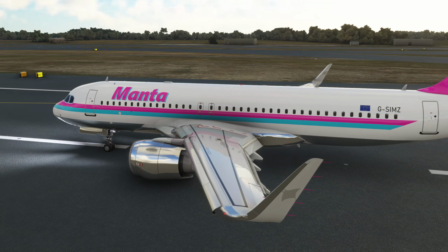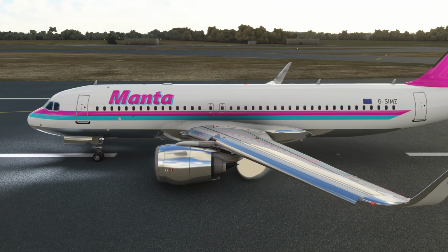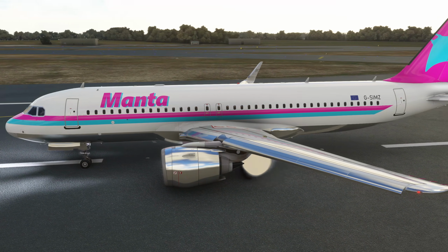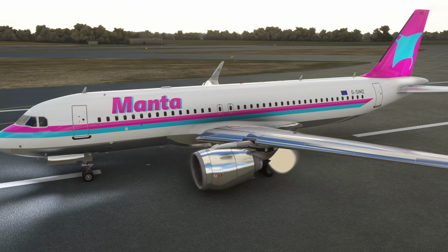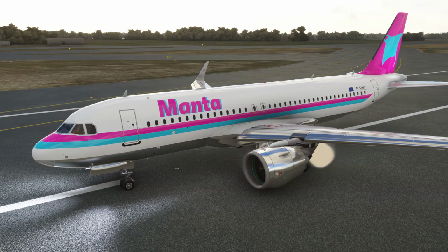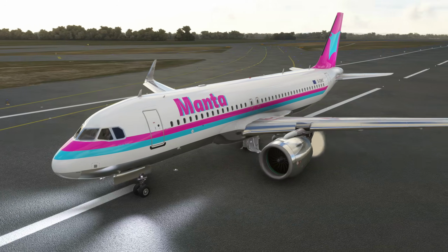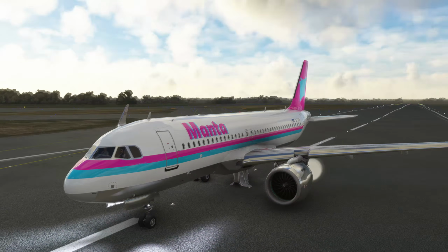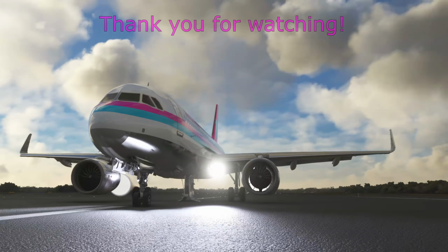Hopefully an interesting video for you, looking at one of the first of many failures we can discuss about the A320 aircraft. Hopefully reassuring you as well that the aircraft is very well designed with robust systems, and that is a very nice version of the landing gear gravity extension that features on a lot of aircraft, but very nicely implemented on the A320. As you can see here, if you see an aircraft taxiing in with the gear doors all down, then that might be a clue that it's had to do a gravity extension of some variety.